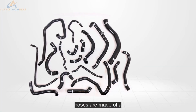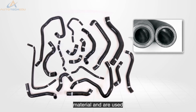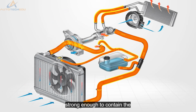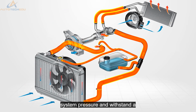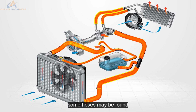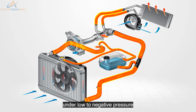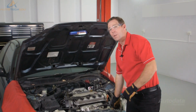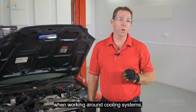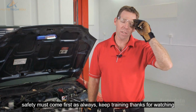Cooling system hoses are made of a layered and reinforced rubber-based material and are used to deliver coolant through the system. The hoses must be strong enough to contain the system pressure and withstand a very wide temperature range. Some hoses may be found with internal springs that prevent the hose from collapsing when under low to negative pressure. Remember, heat and pressure can be a dangerous combination, so when working around cooling systems, safety must come first. As always, keep training.